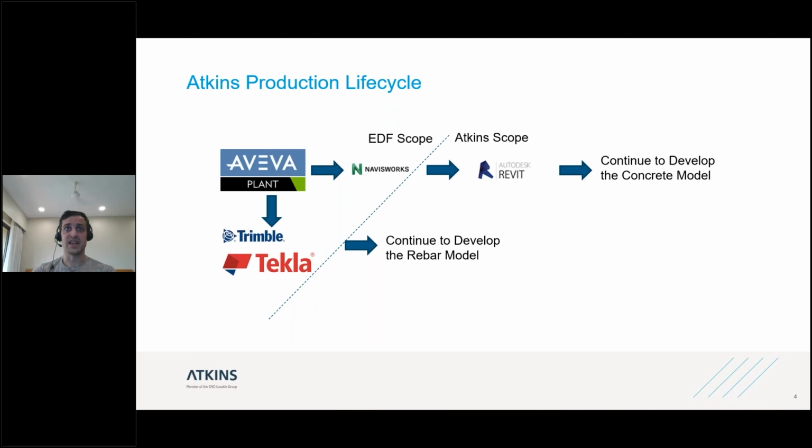They will provide us a Navisworks file, and they have an automated tool that will convert that PDMS model into a Tekla file. We use the Navisworks file to create our Revit model, which is where we contain all of our concrete elements, our general arrangement, our steelwork, and our embedments. And we use Tekla to develop our reinforcement model.